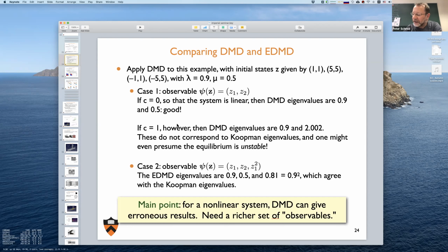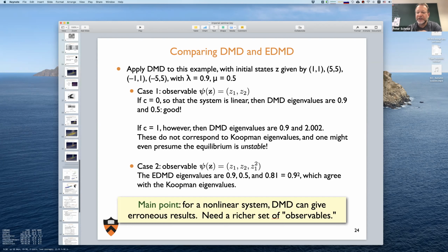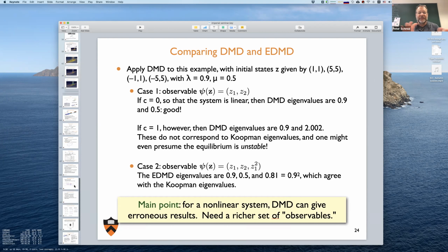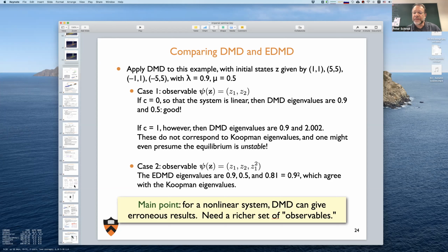For the harmonic resolvent, you go from frequency to frequency, so input to output, forcing to response, right? But often when we do flow analysis, nonlinear or weakly nonlinear flow analysis, there are actually two paths. One goes through a mean flow, which would be of zero frequency, and one goes directly from perturbation to perturbation. Could you separate those two out by using masking matrices or something like that?